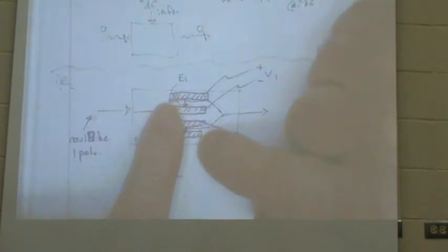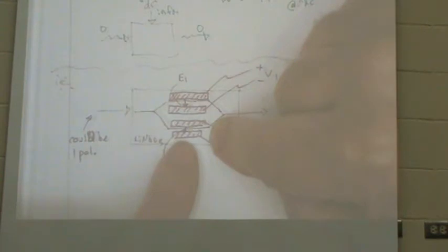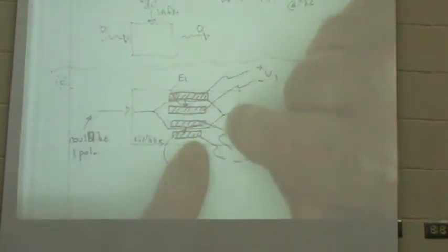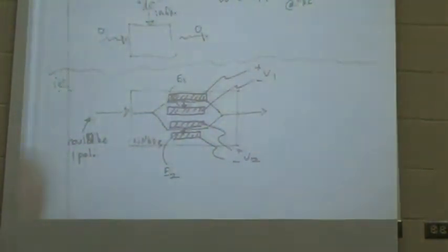Likewise, I do that down here in this path of what's basically an interferometer. Right? I'm splitting a signal. It goes through one phase shift, the other signal goes through another phase shift, and then they recombine here. They're being added back together. Right? Likewise, across these electrodes, I produce this other electric field E2 by applying a voltage plus or minus V2 here. This is an electro-optic modulator.